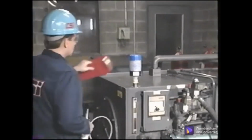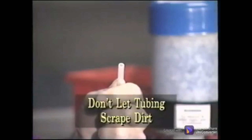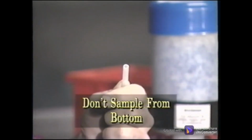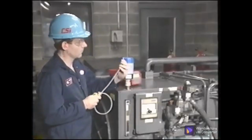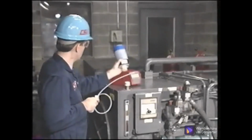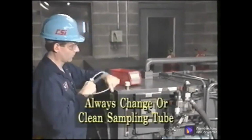When using a suction pump to draw oil up from a sump through a fill pipe, dipstick tube, or other orifice, don't let the plastic tubing scrape dirt from outside the orifice or from the bottom of the sump. On the other hand, if you are concerned about free water in the system, go ahead and sample from the bottom of the sump. But remember, always change or clean the sampling tube between samples.